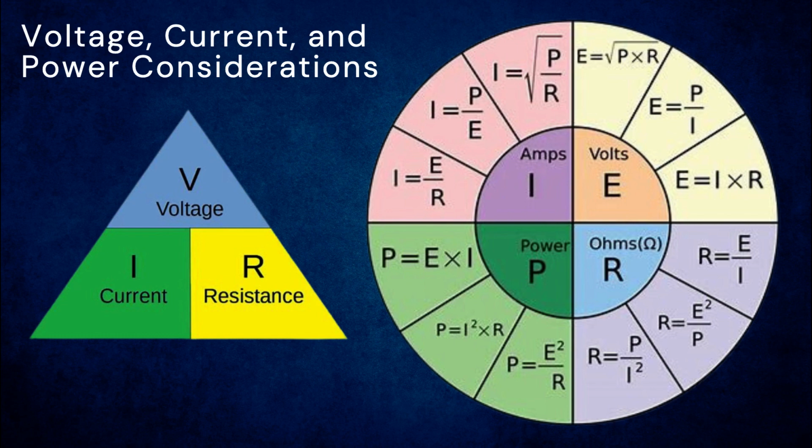Current, flow of charge. Electric current is the movement of electric charge through a conductor and is measured in amperes, A. It signifies the rate at which charge flows past a given point in a circuit. In branch circuit calculations, determining the current drawn by different loads is essential for proper conductor sizing and overcurrent protection. Overestimating or underestimating current can lead to unsafe conditions, such as overheating conductors or inadequate device operation.